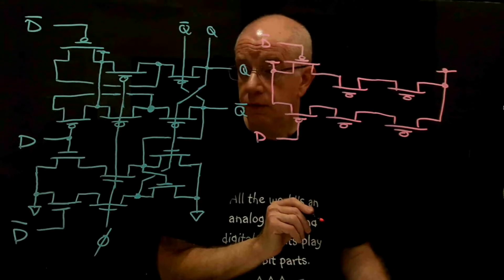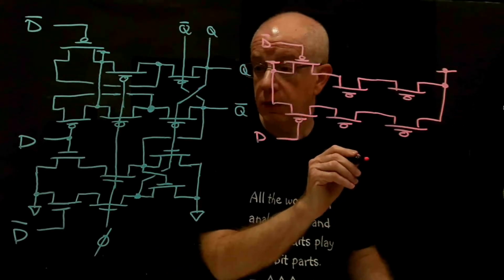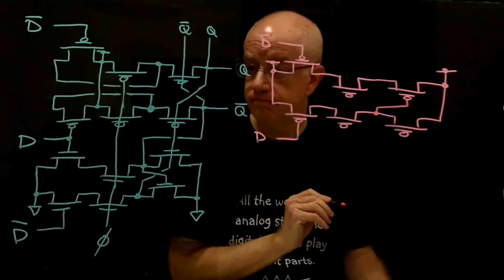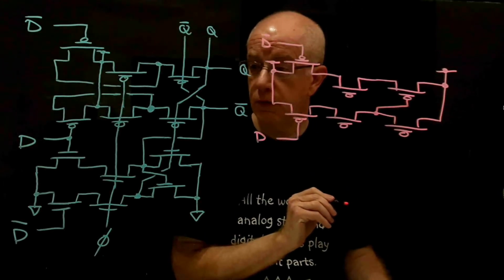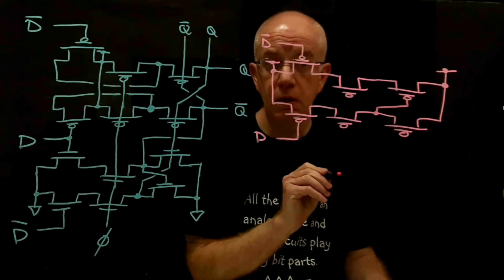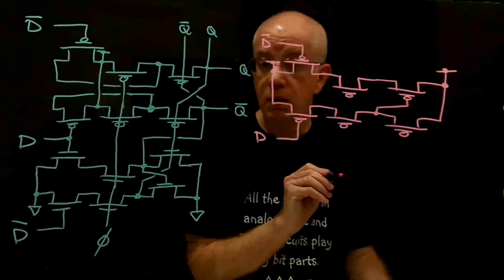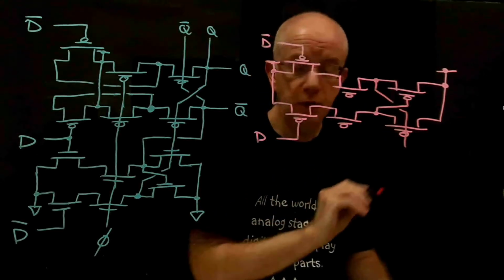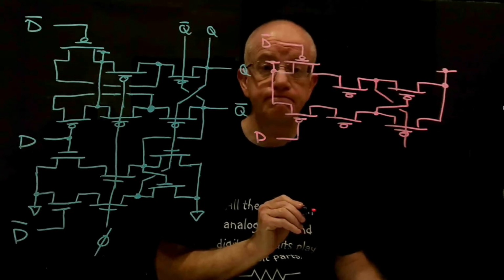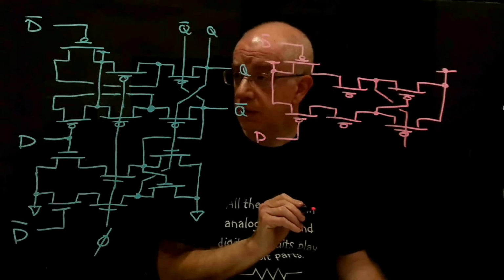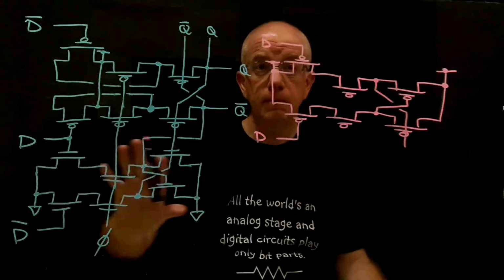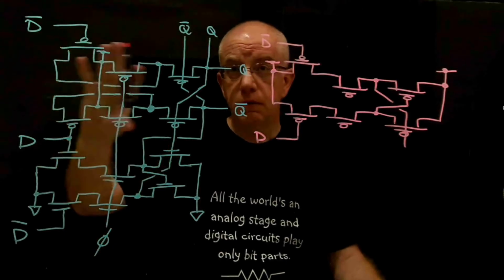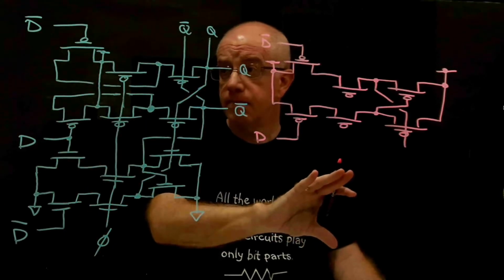And let's see, we have a connection running from this gate there, and we have one running from, see, this one goes over here and jumps over that one and comes out the gate there. And so that's the PMOS section that corresponds to this part down here. Okay. So then we have to do this part, which is going to turn into an NMOS part.